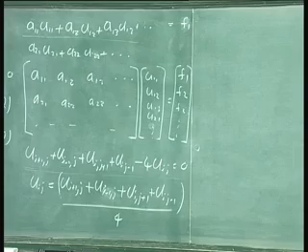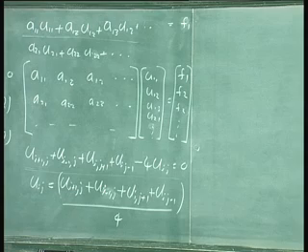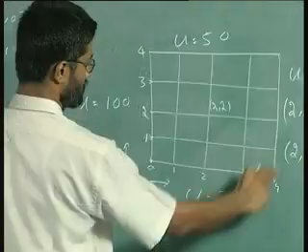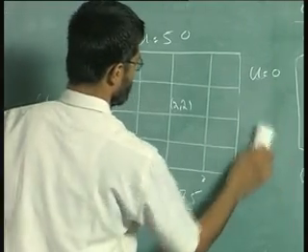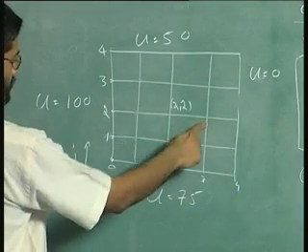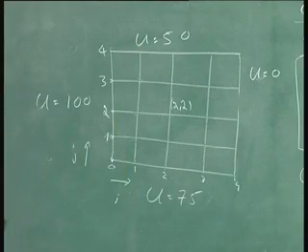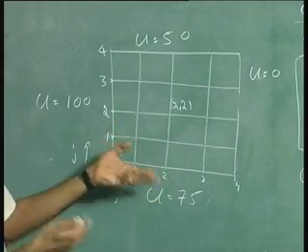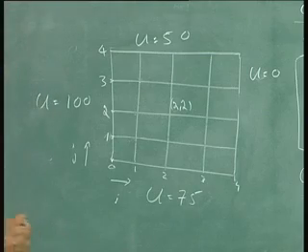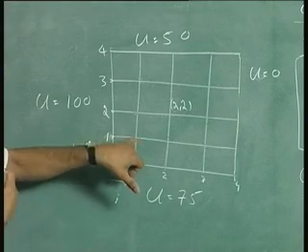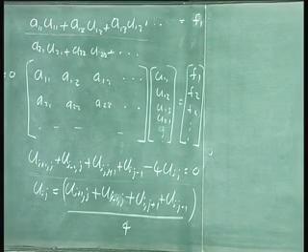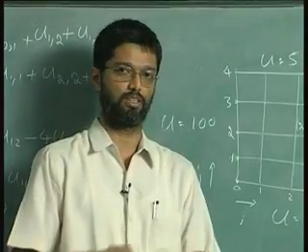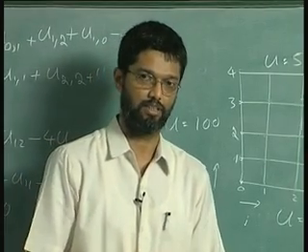In this particular example, we know the boundary conditions. So on my grid, the boundary points are fixed with different u values. Then I start with the interior points all given some temperature, let's say 0, and then I evolve it using these equations. After some time, I will see that the values inside keep changing at every iterative loop, and finally it will come to a point where the temperatures don't change anymore, and then I say that I have reached a steady state.